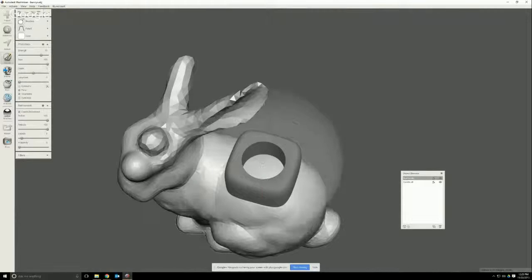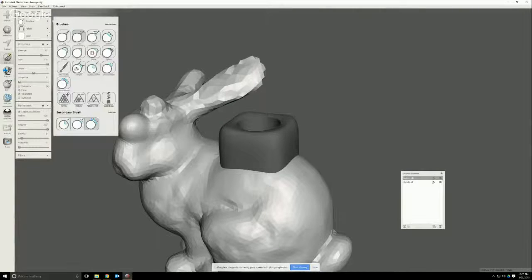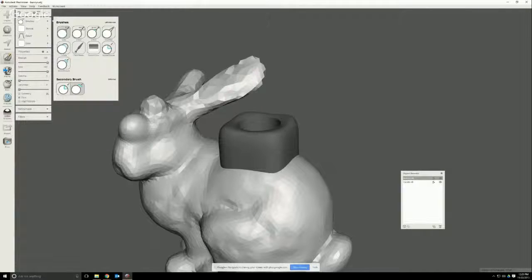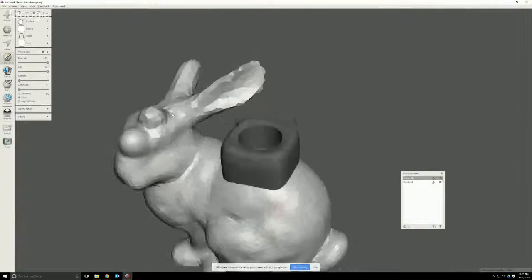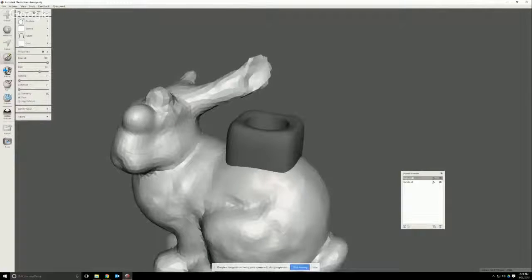You just want to affect the surface on top. If there happen to be very complex things going on underneath, this bubble goes deep into the model. So it's better to switch to surface to a draw command like this, which is only affecting that one side of the ears. And you can kind of see the disc of this brush rotating on this.